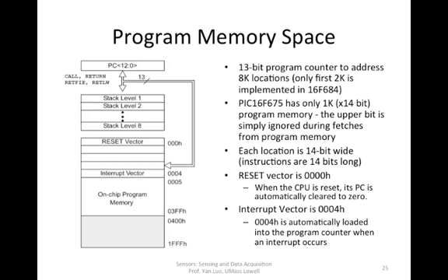You can then, by design, have a special segment of code to handle this case. For example, if you want to read the value from the special registers to another register, you can have this interrupt service routine and have the first instruction of that special segment of program located at address 4.